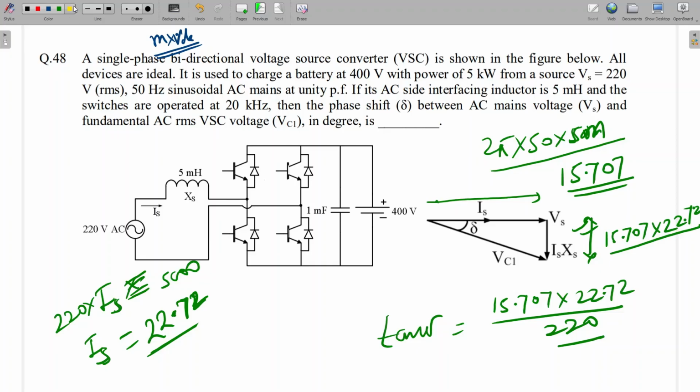So how can we do this in an experiment? Let's say this is 220 volt AC. One voltage we already know. According to this information, we will track this theta value by using a PLL. We'll track this theta, and based on it I want some difference, so I will shift that waveform, and accordingly the modulated signal for this one will be shifted by a delta value.